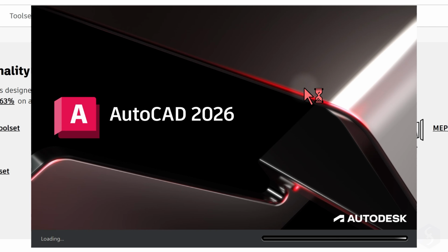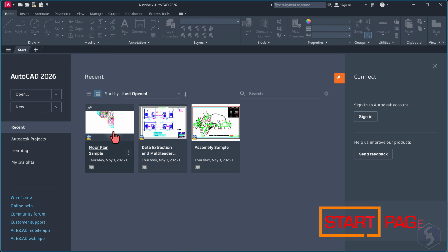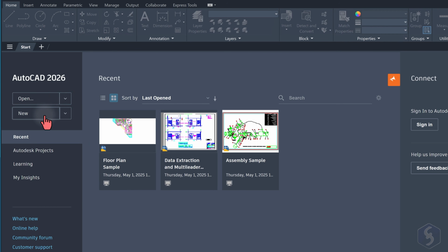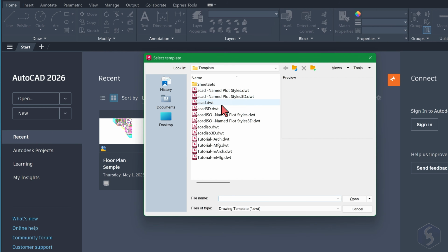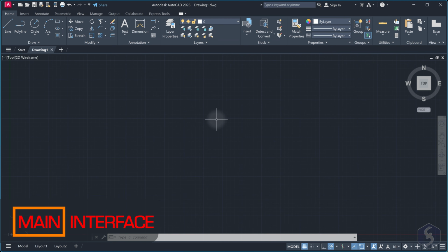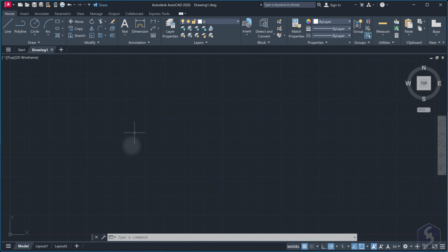As you launch AutoCAD, its Start page opens. Go to open an existing project and select New to start with a new project. In this case, select one of the templates available, fixing settings like unit types, precision, or layer names. Simply pick the default ACAD.DWT template. The new project opens on the main interface, showing a large preview where you realize your design.